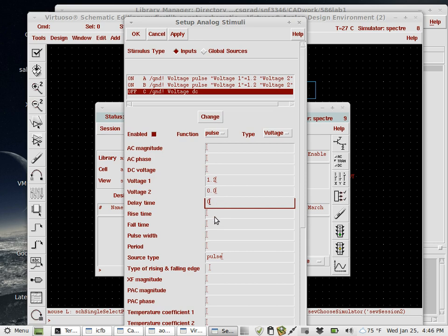Whenever you want to simulate with pulse waves, it's always a good idea to double the period from one pulse wave to the other, so that you have all possible combinations. Sometimes the number of inputs will not allow you to. If it's a lot of inputs, then you should probably do DC. It's probably easier.